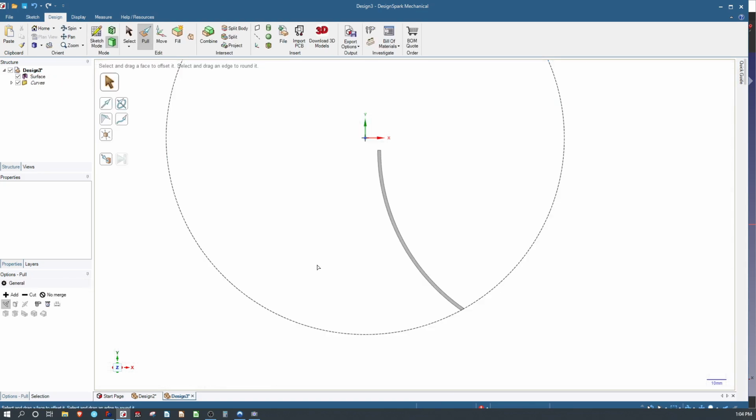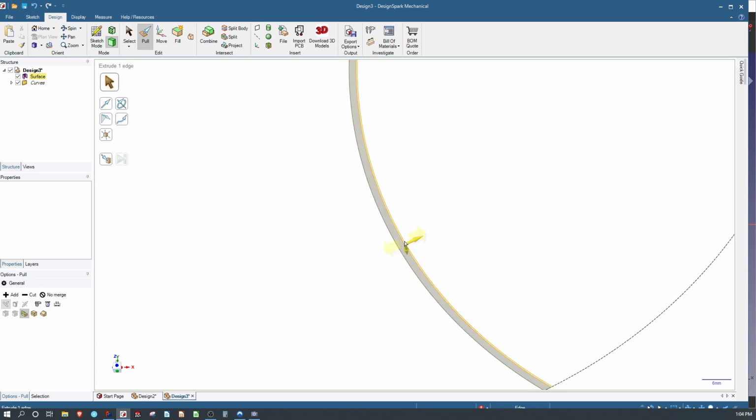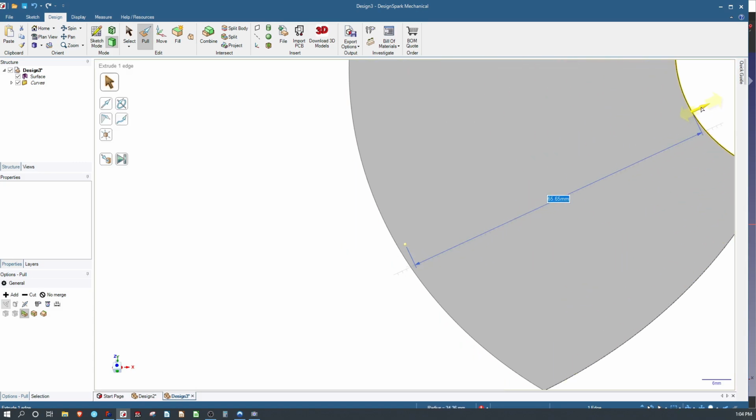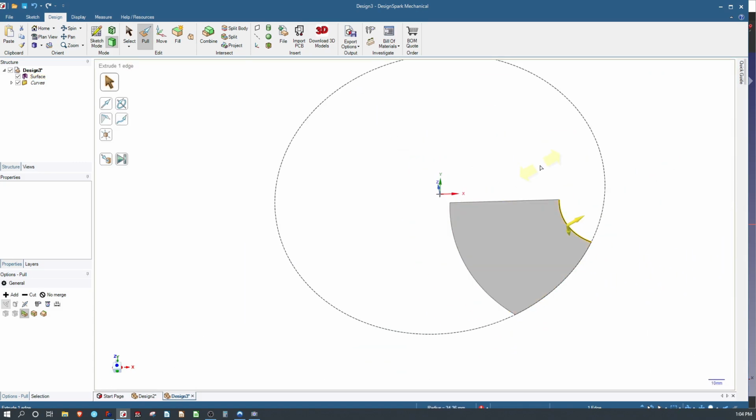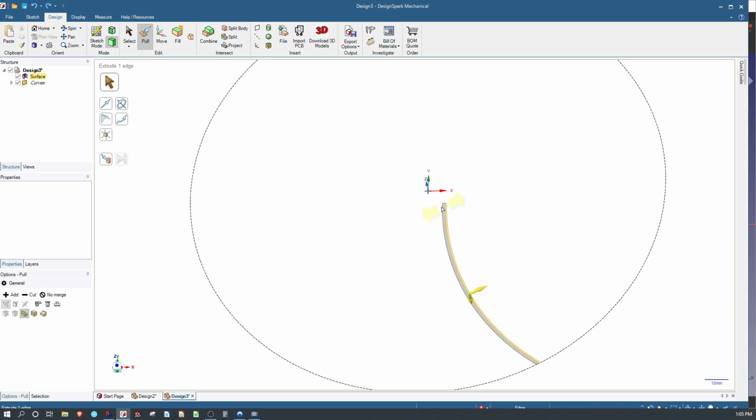We're going to end the sketch here, and now we have a surface. And of course, we can direct edit, the opposite of parametric. We can direct edit elements of this if we wish, right? So we cannot go back and edit our sketch, but I can do things like grab edges and alter the profile of the edges quite dramatically, as you can see. I'm going to hit Control-Z, though, and go back to what we were originally editing. So instead of having a sketch, we're given a surface that we can direct edit.